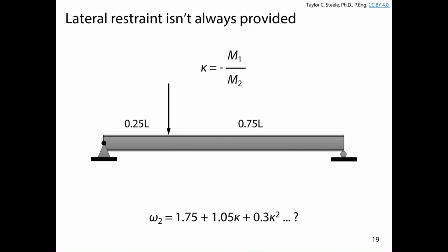Well, just imagine that you've done that before. You're trying to lift something heavy, you've got a beam suspended from the ceiling and a little trolley, and you're trying to lift off the center of this beam, or at 25% of its length. You're pulling up some heavy load, and it's just hanging from a chain, or a rope. From this side to this side, the compression flange isn't braced anywhere along the length. Do you think that a heavy block hanging by a rope provides lateral restraint to that beam against lateral torsional buckling?